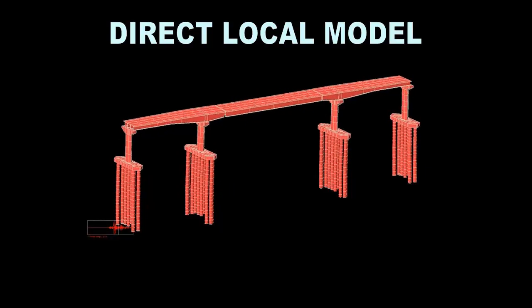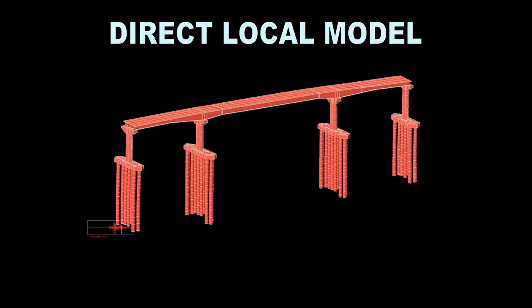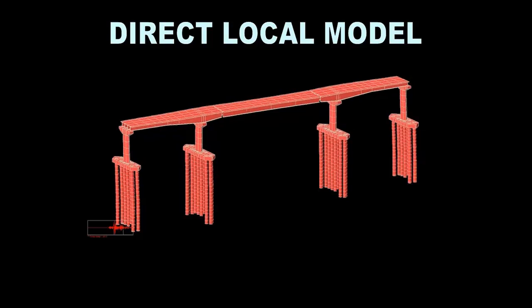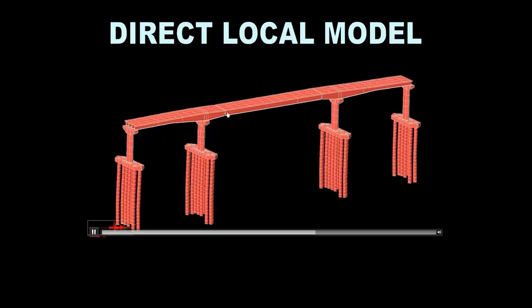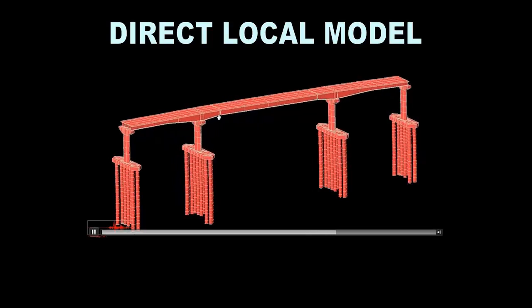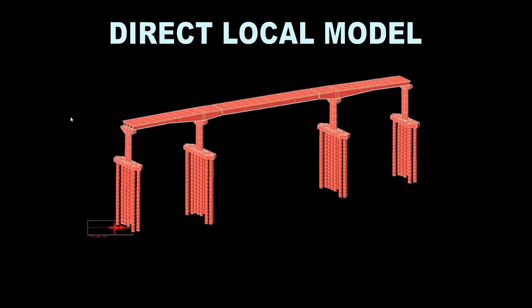When we looked at the acceleration record of the bridge, we saw a lot of spikes at this location, and when you look at the model, you can see how this span is hitting these two cantilever portions, and that's one of the reasons we're getting a lot of spikes in the recorded motion, which I don't have here, for the interest of time, I didn't show it here.